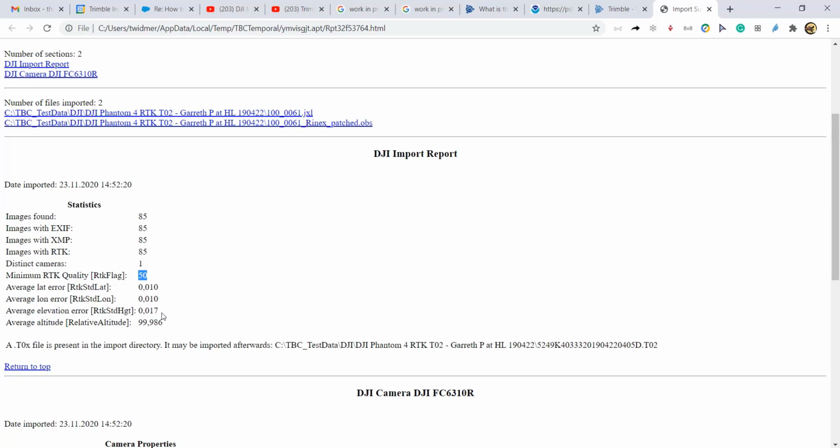Yeah, so it can also be RTK 16 or 34 quality. But when we have the RINEX data and the timestamp files and also these PPK raw files, then we can process our baseline processing in TBC itself, and then we receive our quality. And then we also know based on what quality this is done.